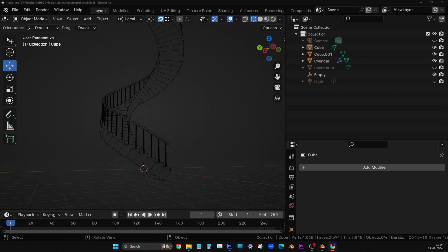Yeah. Now we have to do the same thing for the other side, but before that we can merge this one. So now you can switch on the X-ray mode. Now this view need not be changed. Let it be like this only. This view is okay. Now you are in rectangular selection in the toolbox. Okay. Now you draw the rectangle and select those two vertices where you snapped. Yeah, very good.